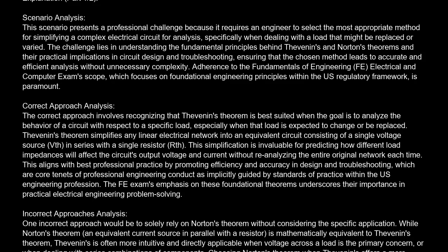The correct answer is A. Employ Thevenin's theorem to represent the network as a single voltage source in series with an equivalent resistance, which simplifies the analysis of how different load impedances affect the circuit's output. Explanation. Scenario analysis. This scenario presents a professional challenge because it requires an engineer to select the most appropriate method for simplifying a complex electrical circuit for analysis, specifically when dealing with a load that might be replaced or varied.